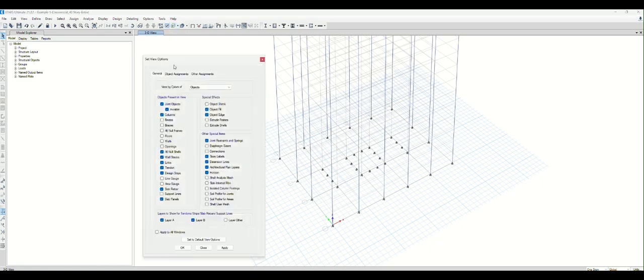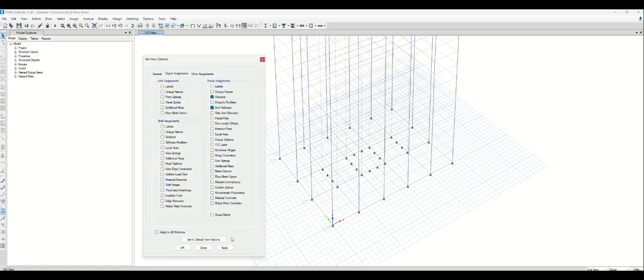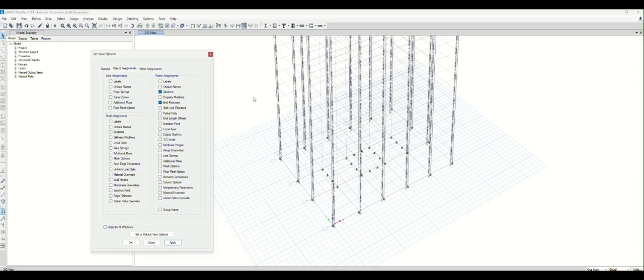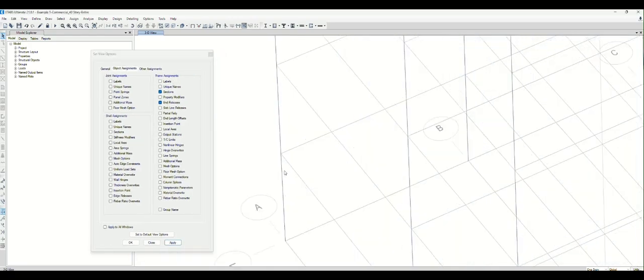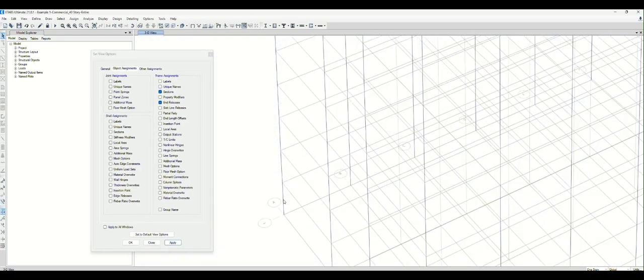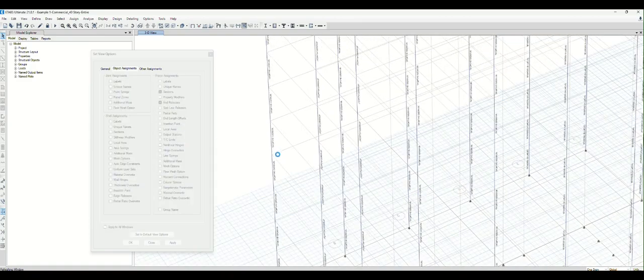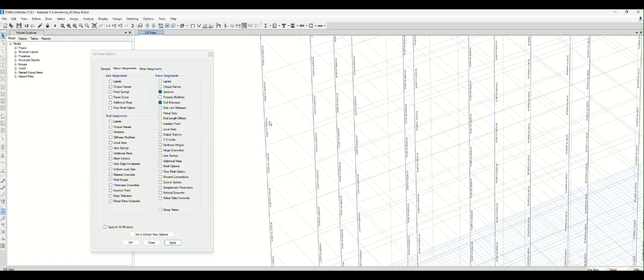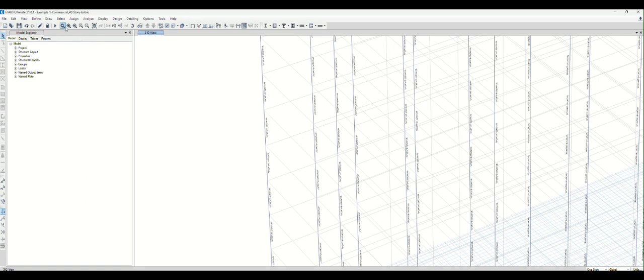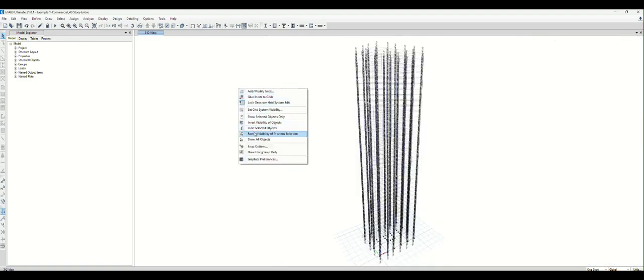I'm gonna turn on the section and see the member size is maintained. Oh, 14 by 342. Here, 311. 283. So you see that sizes gradually reduce. All right, so at this point, we just complete the column design.